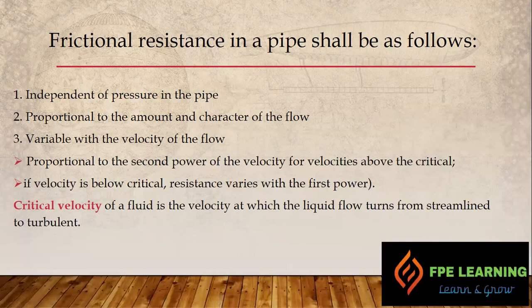For example, if you are pushing water to flow inside a 2-inch pipe, a 500 GPM flow inside a 2-inch pipe, we need higher pressures to put that through. And at the same time, we have higher frictional loss. So we have to be careful regarding the size of the pipe and amount of the flow so that we can avoid the friction loss in the piping.